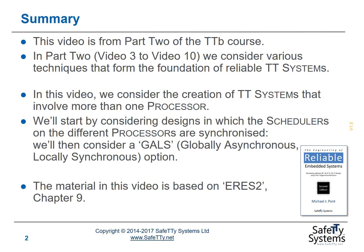We'll start by considering designs in which the schedulers on the different processors are synchronized. We'll then consider GALS designs. These are globally asynchronous, locally synchronous options. So in a GALS design, different parts of the system are synchronized internally, but the overall system need not be fully synchronous.